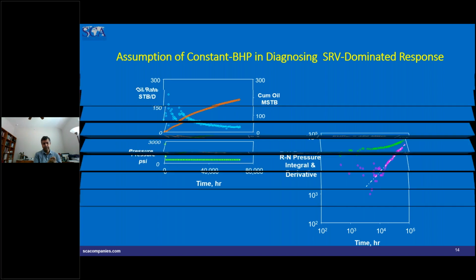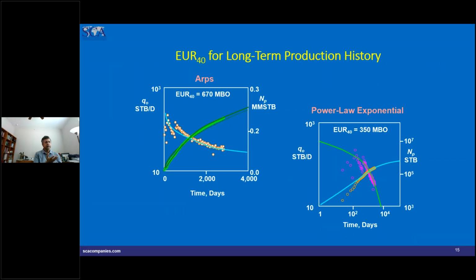Okay, we can do the parallel exponential and also Arps. As you can see, Arps will always give you an optimistic solution. Hence my preference for either power law or similar tools, and or stretch exponential. It'll give you a very similar solution, whereas conventional Arps will give you a very optimistic one.